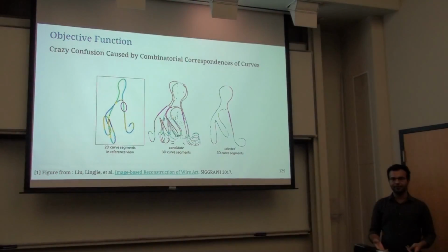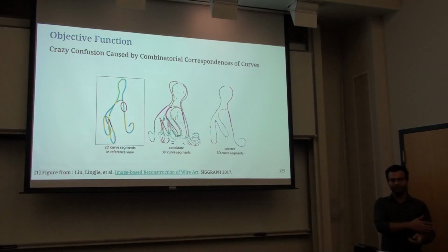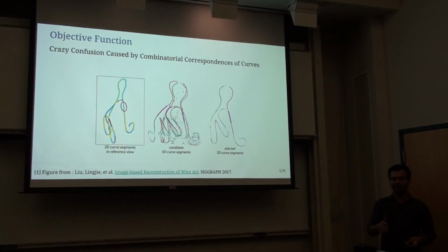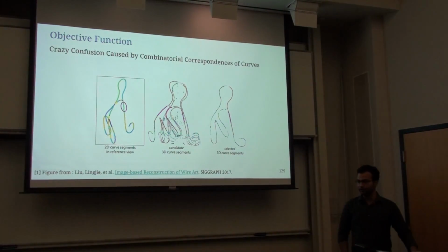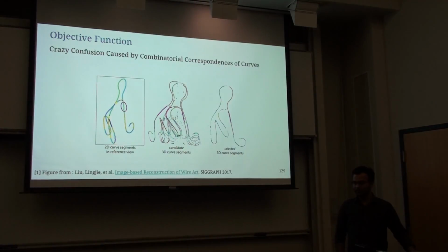If you have multiple wires, then you can take inspiration from something like LSD-SLAM: take the previous depth estimate, reproject that into the current depth estimate, and do some sort of curve-to-curve correspondence. And if there are a lot of curves intersecting there, I guess then you can have a similar 3D. So our version of this would be that catenary curves are longer, and we maybe have some idea of the maximum number of curves which we saw in the image over this region. So we have to come up with something like this.